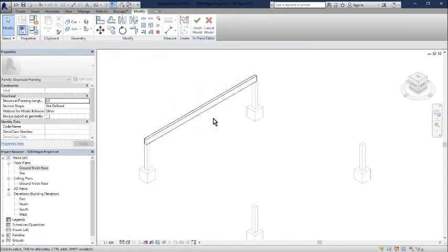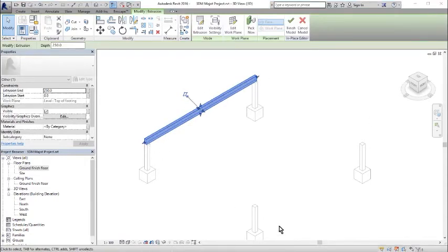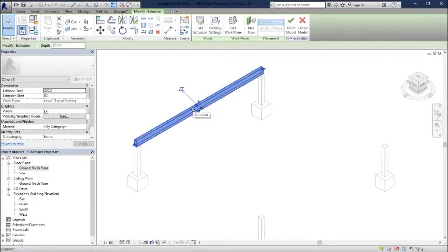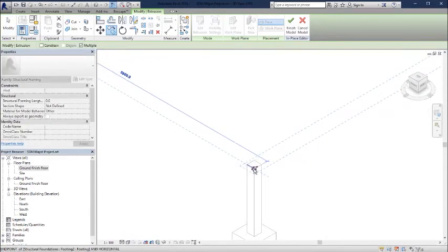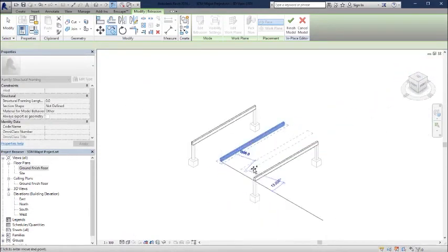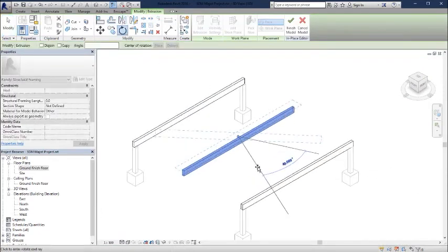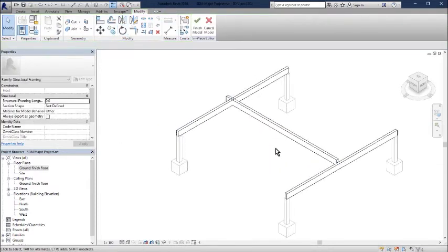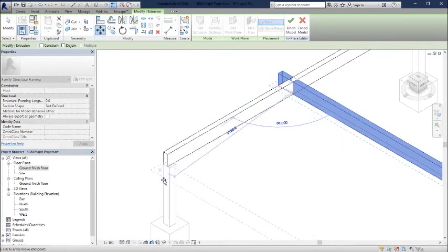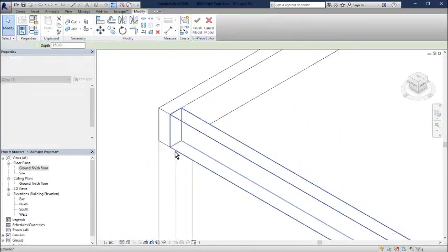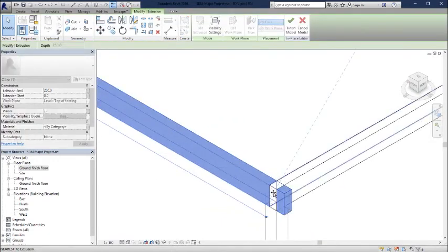And now we need to have this member going across the other areas. So what we're going to do is copy this using our 3D view over to here, and we're going to copy it one more time, and we're going to use our rotate. I'm going to rotate that 90 degrees, and we're going to move this, shortcut MV. So we're going to move this all the way to here, land that there, and then we are going to adjust this to line up there